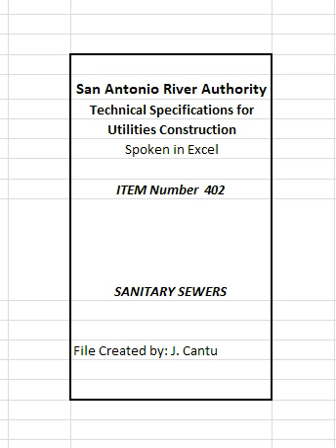7. Laser beams. The use of laser beams for vertical control shall be required provided the contractor makes available to the inspector, when requested, a level and rod of sufficient sensitivity to accurately determine differences in elevation between points 300 feet apart with one instrument setup. No pipe shall be installed in tunnels except as provided on the plans, or with the permission of the engineer.